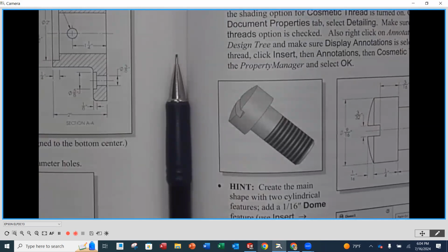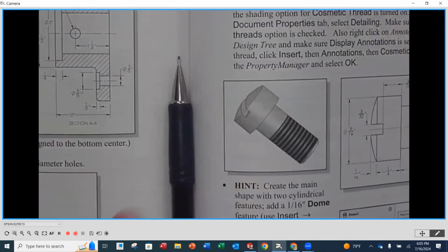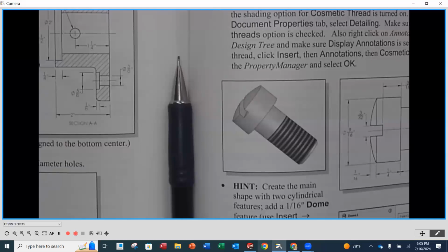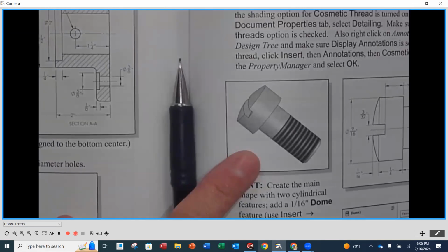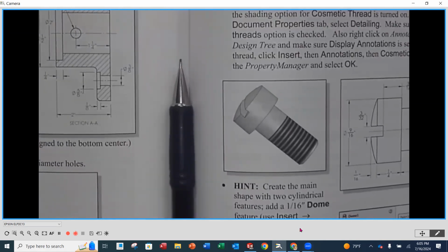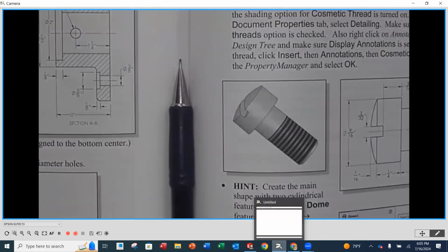Okay. The reason for that is because you need an actual tool in order to tighten or loosen it. A slot head, you could use a butter knife, you could use a coin, and you could actually remove it. But by OSHA standards, when we're dealing with guarding, especially in an industrial setting, or any type of machinery, we need to have an actual tool to tighten and loosen it. And that's why we see socket head cap screws used a lot, or those Allen heads or torx heads, rather than the slotted heads. So always avoid slotted head fasteners or screws for that reason.